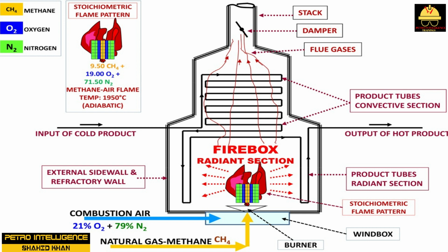Primary air enters the furnace through air shutters located on the burner that premix air and gas within the burner. Secondary air enters through air registers located on the burner. Air also can enter the furnace through idle burners, open peepholes, leaks in the furnace casing or casing joints, or